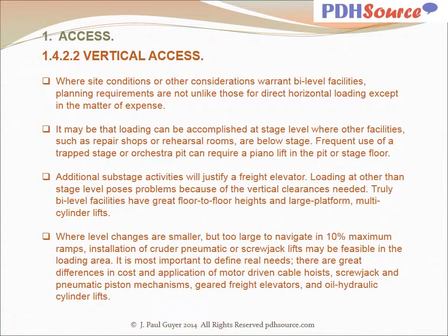Frequent use of a trapped stage or orchestra pit can require a piano lift in the pit or stage floor. Additional substage activities will justify a freight elevator. Loading at other than stage level poses problems because of the vertical clearances needed. Truly bi-level facilities have great floor-to-floor heights and large platform multi-cylinder lifts.